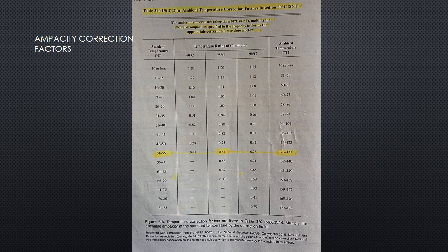And a specific ambient temperature of 86 degrees Fahrenheit, that is 30 degrees C, in tables 310.15(B)(16) and 310.15(B)(17), and 104 degrees Fahrenheit, that's 40 C, for the other 2 tables. When there are more than 3 conductors in the raceway, or the ambient temperature differs from the table values, corrections must be made.